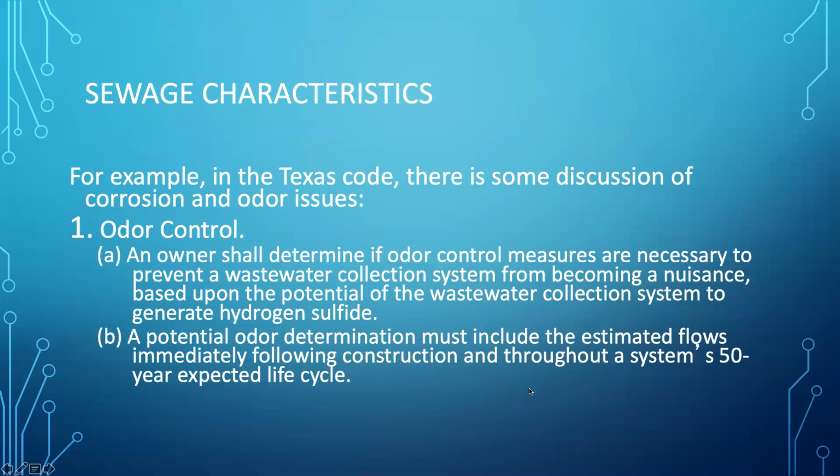There's also odor control. In Texas, an owner shall determine if odor control measures are necessary to prevent a wastewater collection system from becoming a nuisance based upon the potential of the wastewater collection system to generate hydrogen sulfide. Pretty much any wastewater collection system is, by definition, a hydrogen sulfide generator.